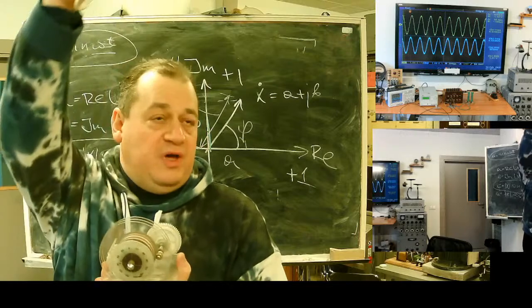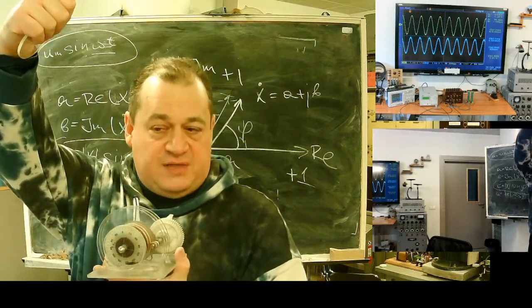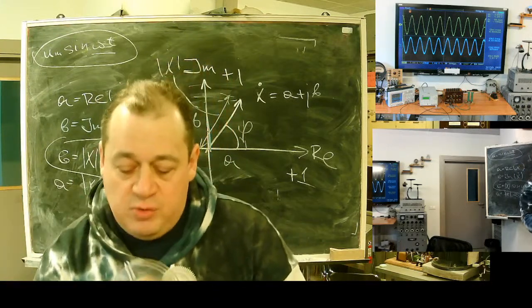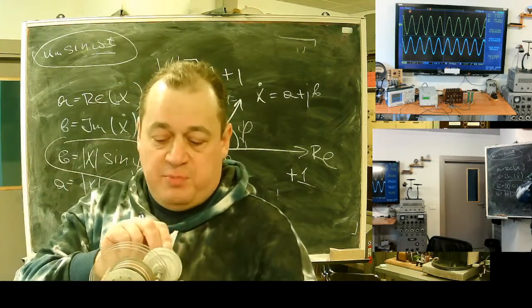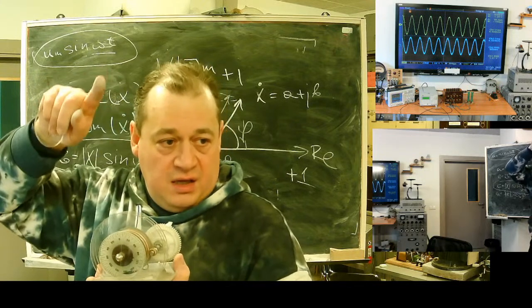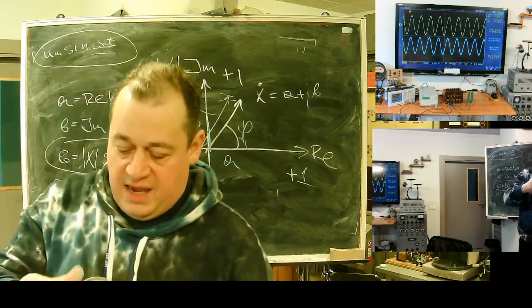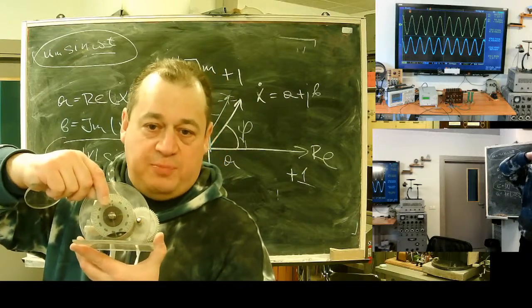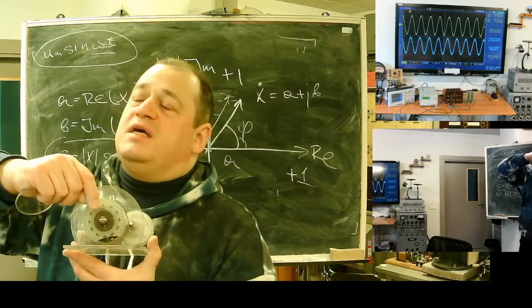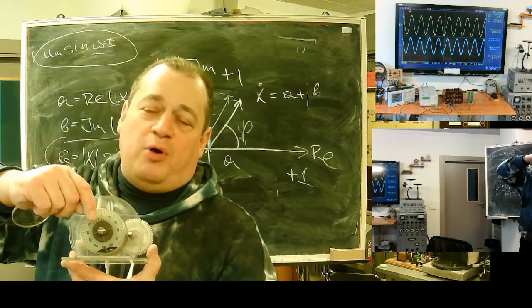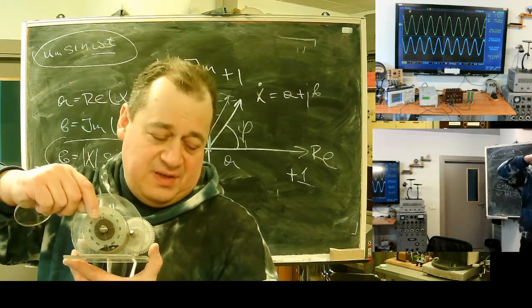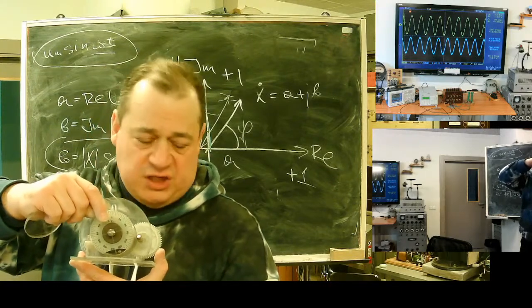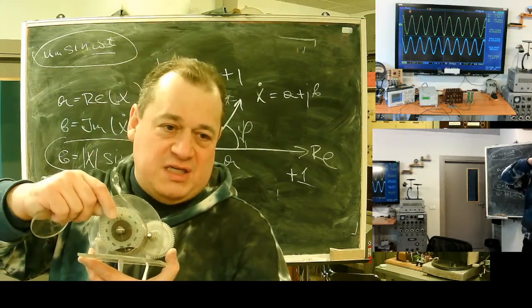Time goes up if we speak on sine as in power industry. Time goes up. Voltage produced by this generator can be assumed as a projection of this small vector representing it. It's from Park decomposition. Okay, it's from electrical machine.